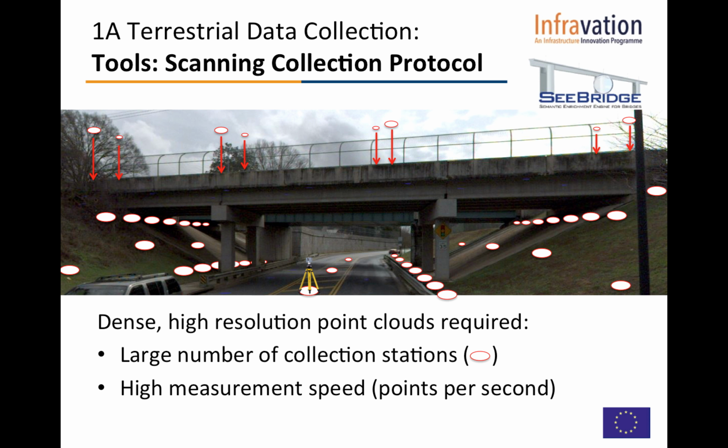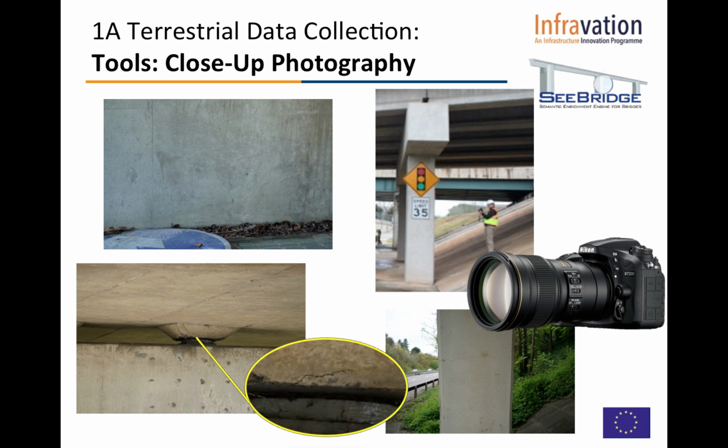A laser scanner device placed under certain positions and moved around these bridges and so forth. Then for the collection of the second set of data, that being the photography, we essentially just used a very simple setup of a digital camera with a nice lens on it that allowed us, even though we were standing very close, to get very accurate, high density, high resolution photographs of the bridge structure itself.